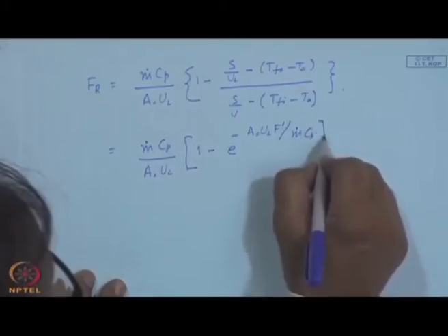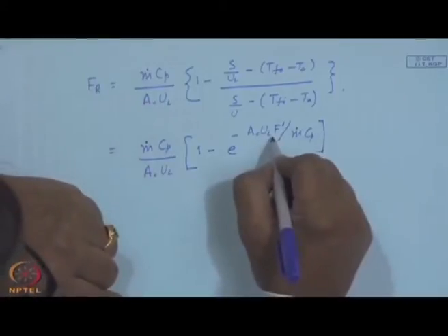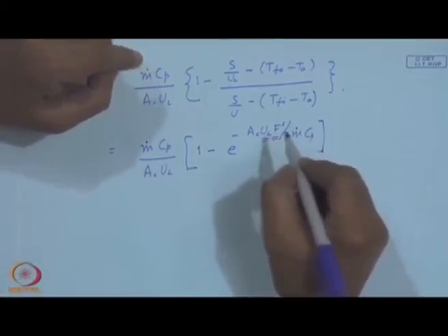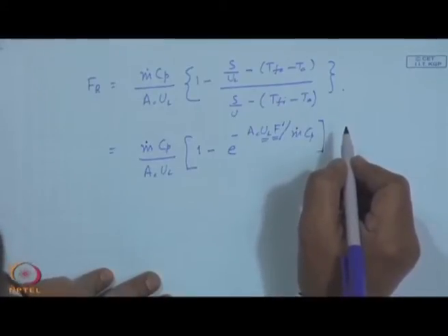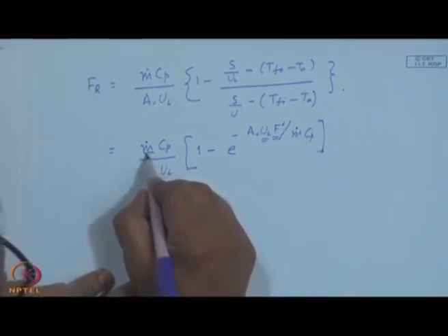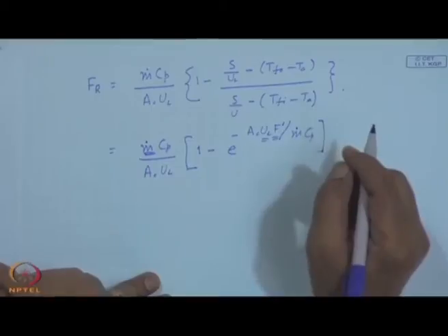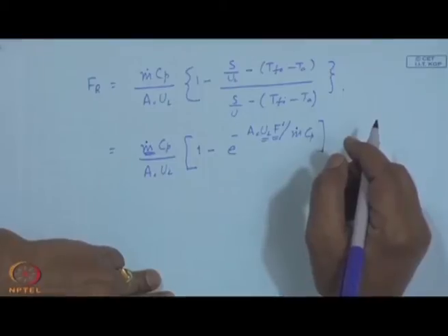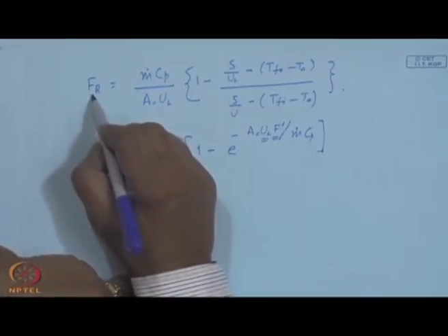So, if you look at this particular equation, the heat removal factor, in addition to containing f dash and the loss coefficient, where f dash contains the thermal conductivity of the material, spacing of the tube, geometry in general, contains an additional factor m dot. So, the flow rate indirectly is going to influence your heat transfer coefficient, even if that is not very significant unless the regime changes from laminar flow to turbulent flow. You have got the effect of higher m dot reflected in F r.